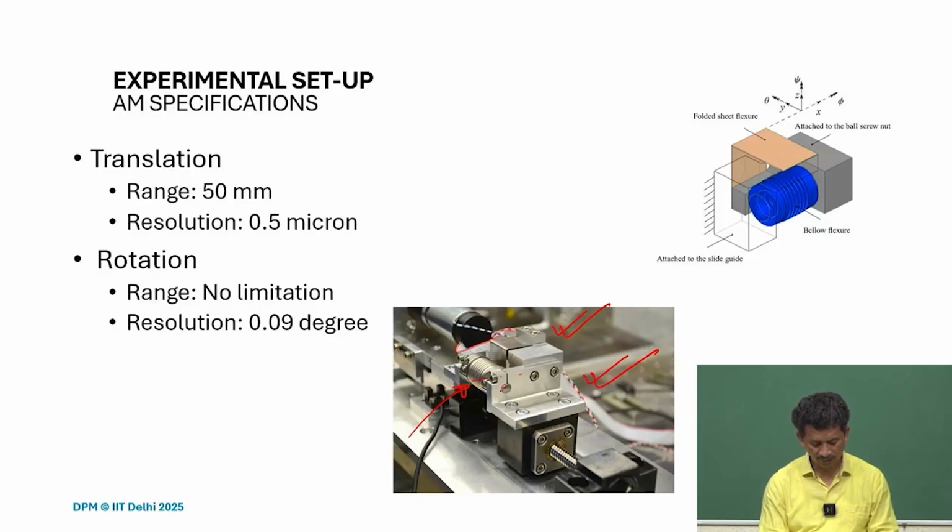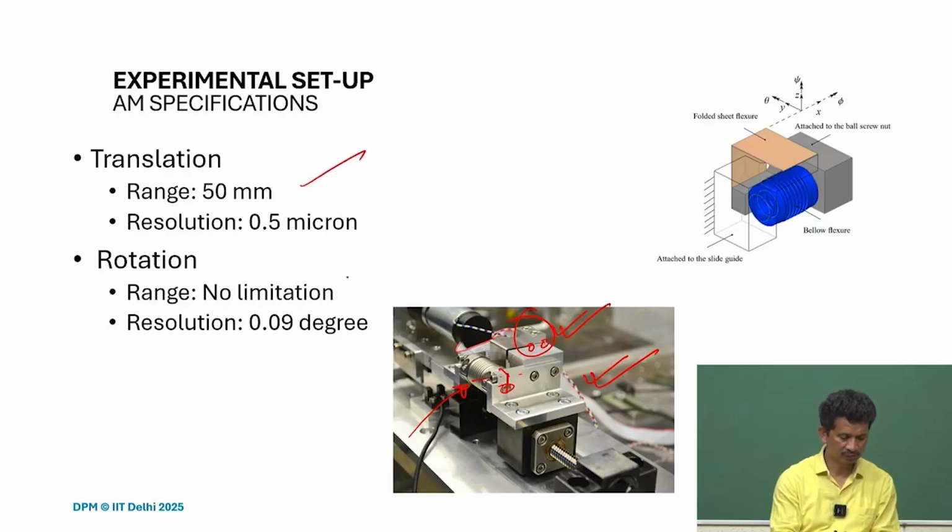what you can see is to fix it we make a cut, a slit, so we are using the flexure property to clamp it. We are not clamping the pin or the shaft directly. There is also the question of how to clamp the sheet flexures in order to avoid a kind of micro slip. We have to design those clamps properly. So you can see the small edges there which are holding it. Very important. So yes, ultimately this is what we achieved.